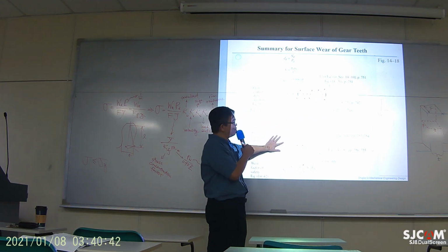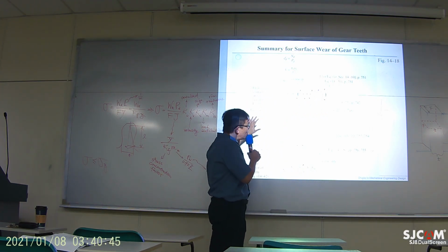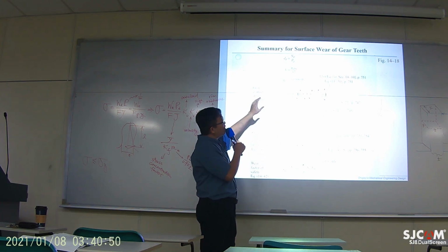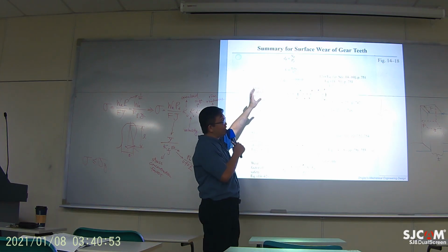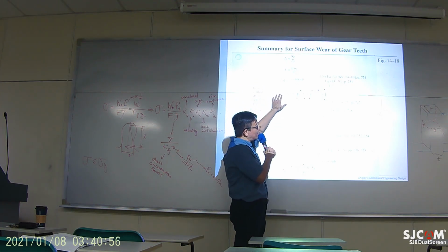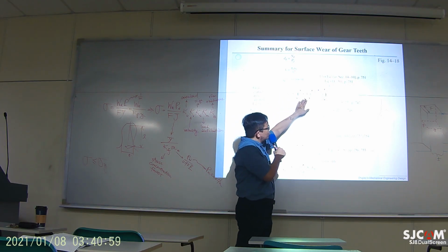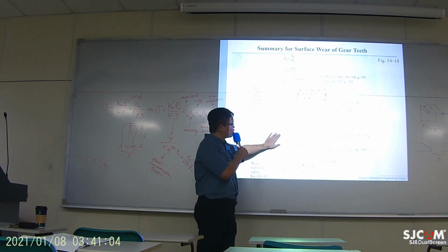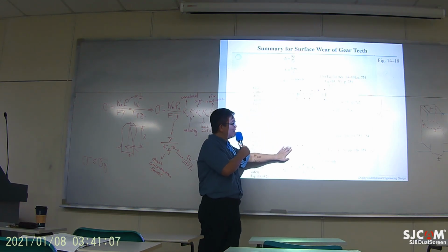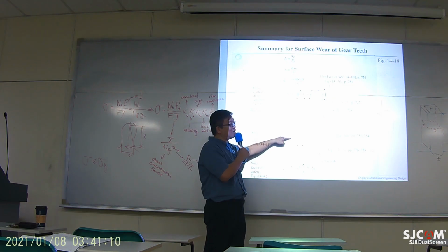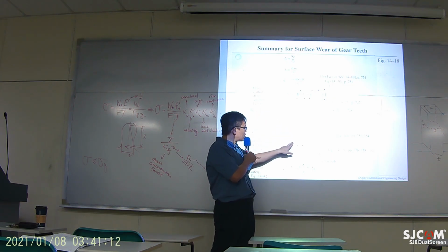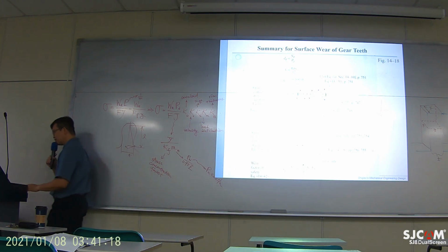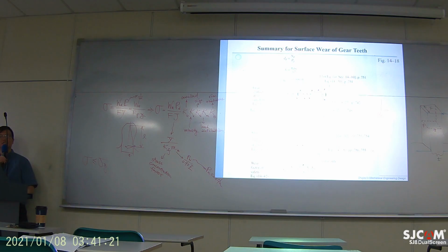The contact stress has a limit as well. So the second type of failure of the gear is surface wear. The idea is to estimate contact stress, which is corrected by different factors, and that stress has to be smaller than a certain limit. This limit also is an allowable contact stress with correction terms. So that would be the second failure mode for the gear.